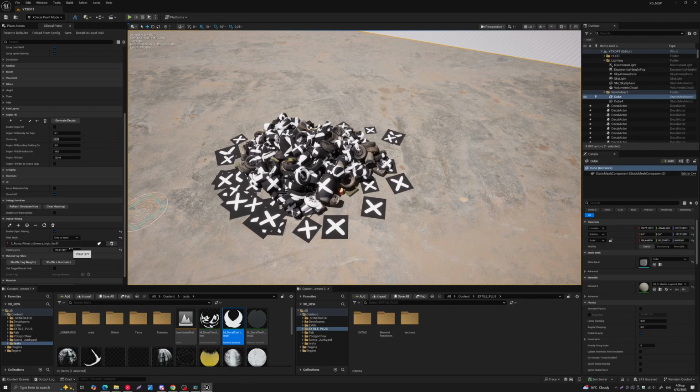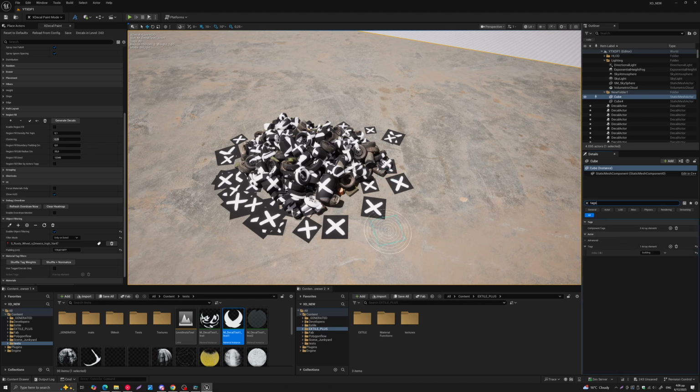The last thing I want to show you about the object filtering is this tag system that I have here. Now, in Unreal, you can add tags to any actor in the details panel. So if I come here to tags, you'll see that we have this naming of a tag here. Once I select an actor that has a particular tag, and I click on this little tag icon here, then all other actors that share the same tag name will also be filtered.